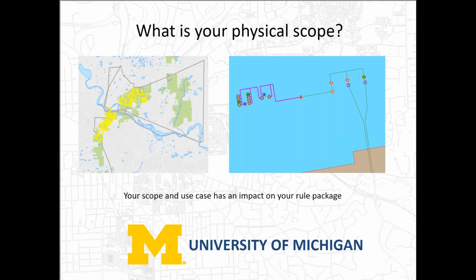Larger utilities stop at the meter at the side of the house or the side of the building, and they don't go inside. We've got 340 substations that are inside the buildings, and so we transfer from outside the building. Typically it's underground, inside, and so how you handle conductors going inside the building is very important.